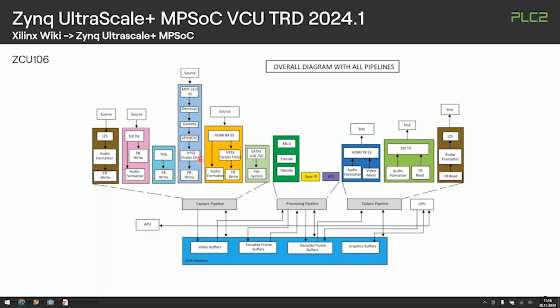One more thing about these video processing units: at times there are IPs that require special licenses for these kinds of data paths. But if you don't want to bother with those, there are also other solutions around for sure. The typical approach is that you go into DDR memory from this input cluster. This is where a video buffer can be allocated, but it's not statically allocated in the design. It's something you can do on a per processing basis. And from there, you can do a memory to memory operation on image processing, for example.